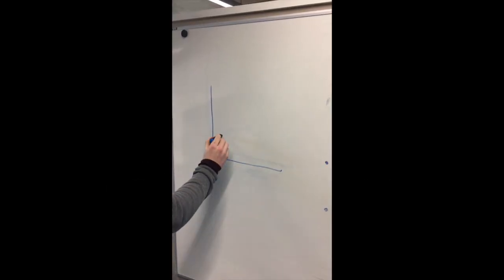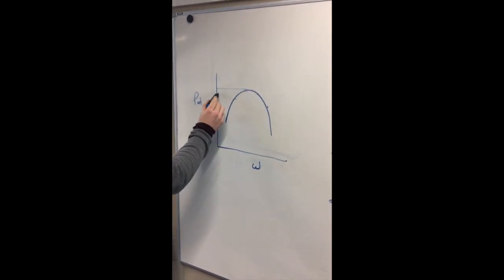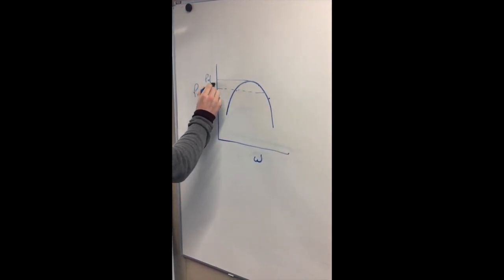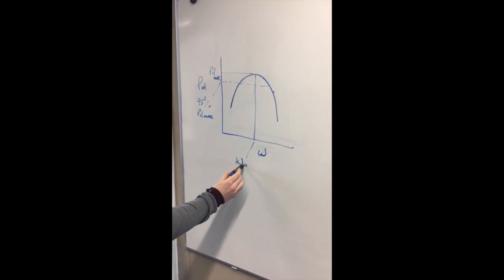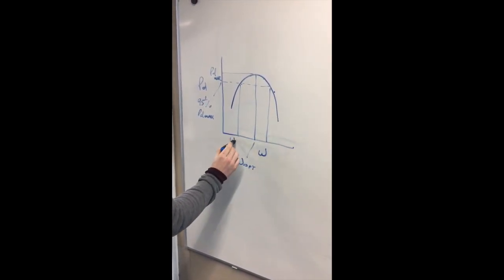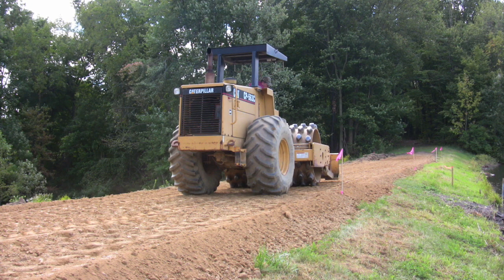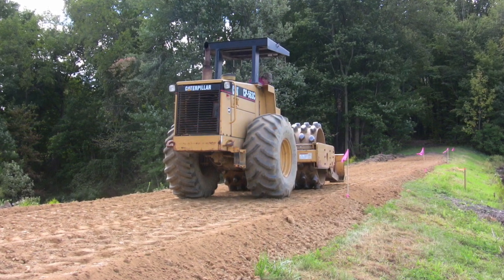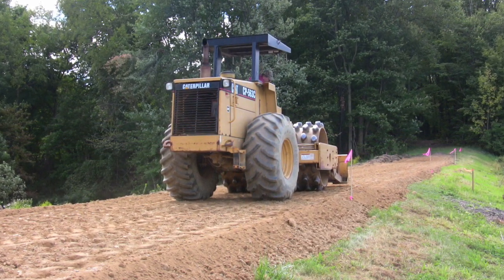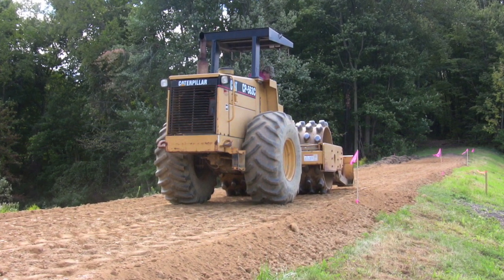So we used the Proctor test in the lab to calculate a dry density value for the soil. We then used 95% dry density max value to get our range of values for our soil to get correct moisture content and density values that we could use on site. Most common practice on site is to use a sheep's foot roller, as this gets the required compaction level that is required. It is also common practice to use 225mm lifts or layers.